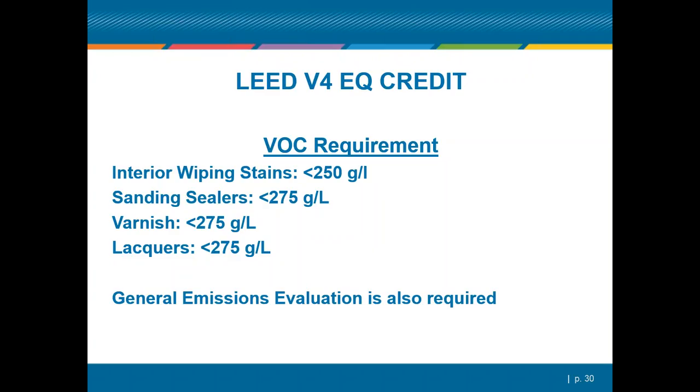Yeah, the small chamber testing aspect of it, that's the major one, because under LEED 2009 we did not have to do small chamber testing. We just had to meet the criteria of the lower VOC categories. And now under LEED version 4, again we have that 90% bucket that we have to have products small chamber tested.